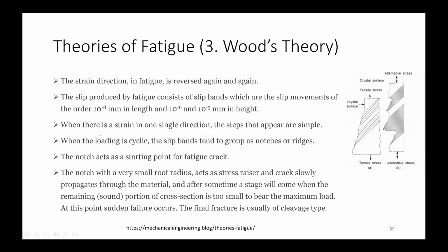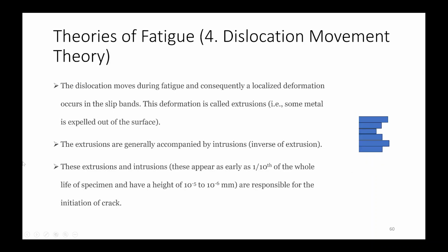When there is a strain in one single direction, the steps that appear are simple, and when the loading is cyclic, the slip bands tend to group as notches or ridges. These notches act as starting points for a fatigue crack.